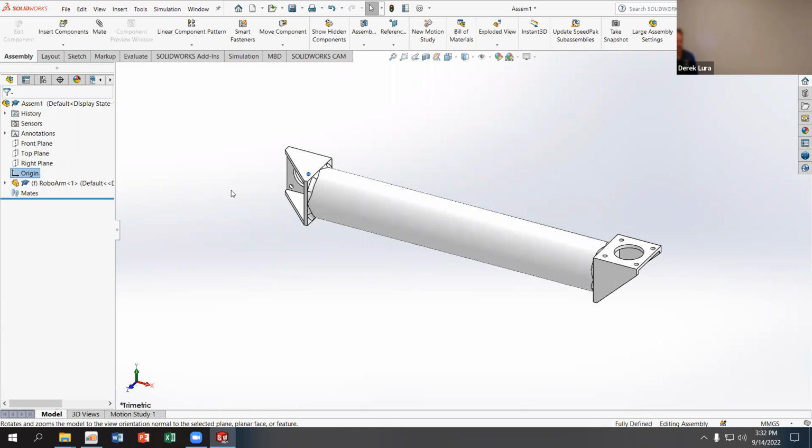My goal with this design is actually to evaluate a generic robot arm that will have a motor on one end and a coupling on the other end, and I can put them together in a series of connections to make a robot that is as long and as complex as I want it to be. Every joint will be at 90 degrees from the previous joint. So if I put 3 of these together, I can actually get kind of any position I want in a fairly restricted volume because the arms are all the same length. But it will work reasonably well.